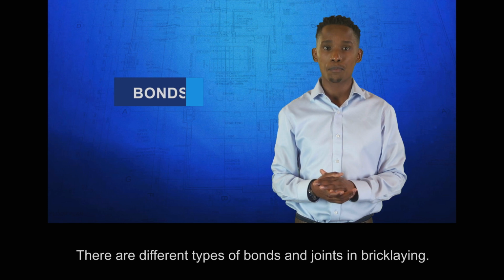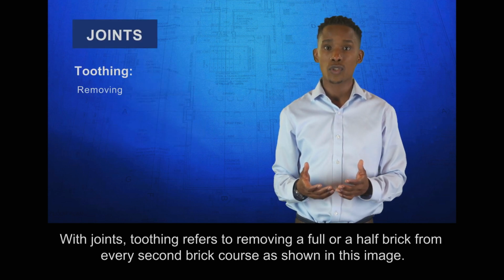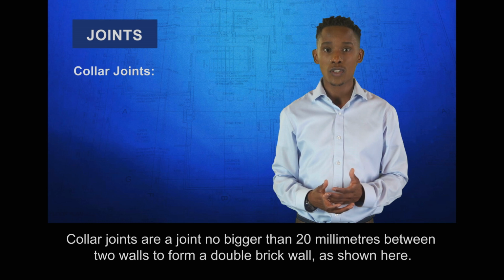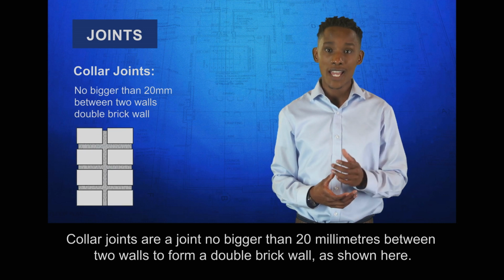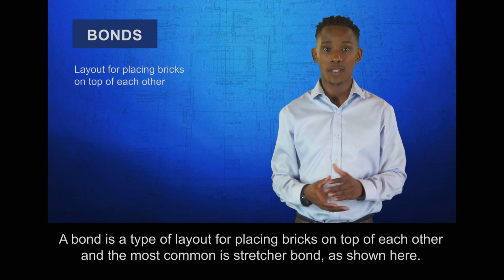There are different types of bonds and joints in bricklaying. With joints, toothing refers to removing a full or half brick from every second brick course as shown in this image. Collar joints are a joint no bigger than 20 mm between two walls to form a double brick wall, as shown here.